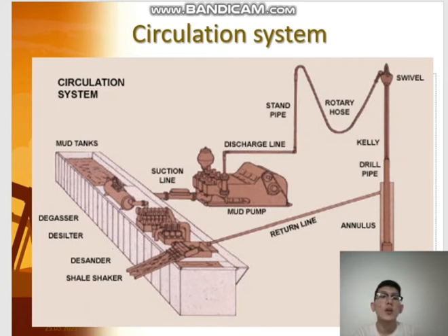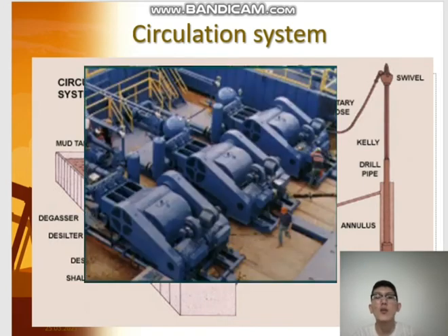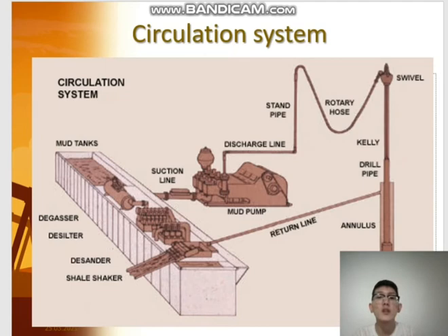Hole conditions require it, the driller can compound or combine pumps to circulate large volumes of mud. In fact, in deep wells the rig may have 3 or 4 compound mud pumps.